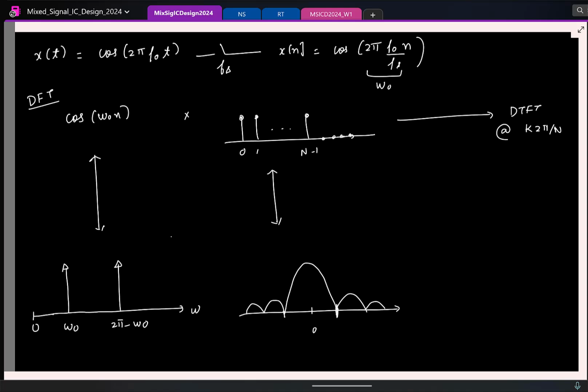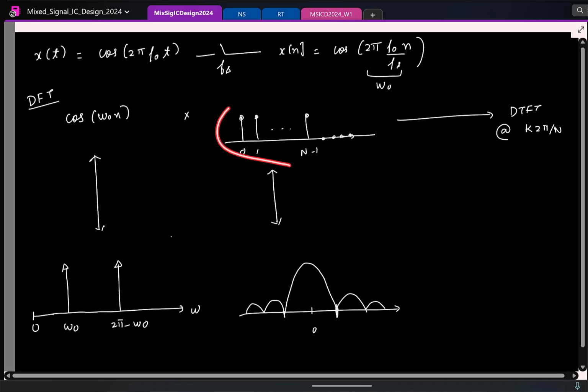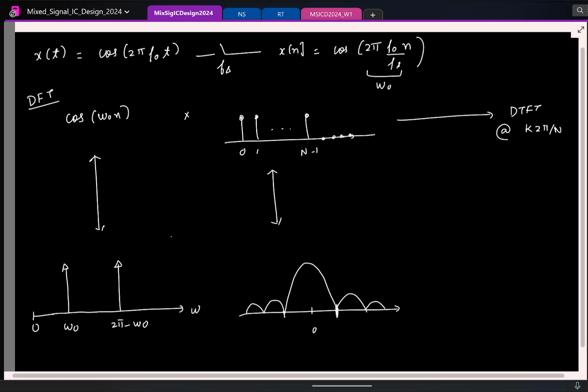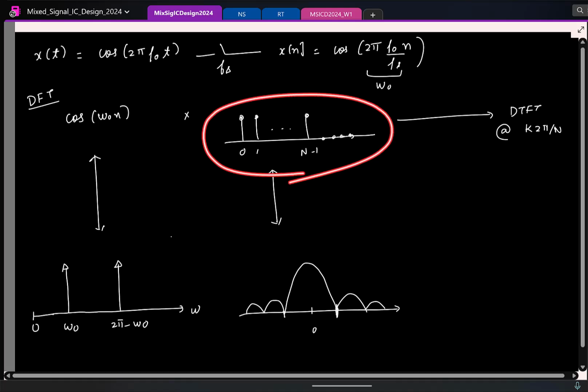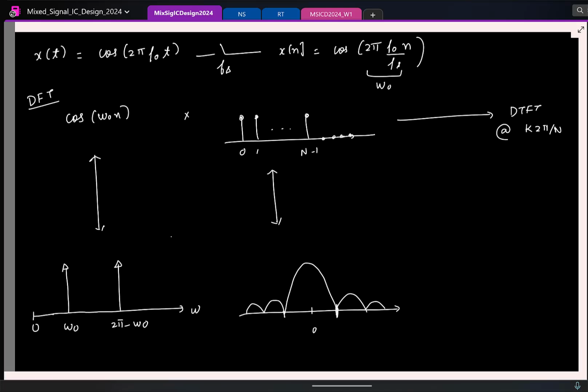See, what do you do in Fourier transform? When you compute Fourier transform, what do you do? In slightly more mathematical terms, you multiply the sequence with sinusoids of different frequencies and take the integration, or summation in discrete time, right? So here when you multiply a sinusoid with this sequence, that's going to truncate the sinusoid. So essentially you are looking at a sinusoid n samples long. And when I integrate it, or sum it, it should become 0.